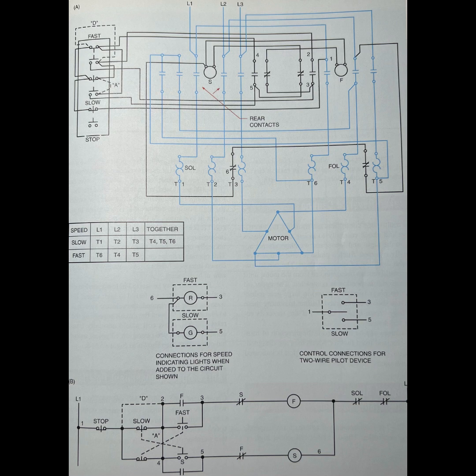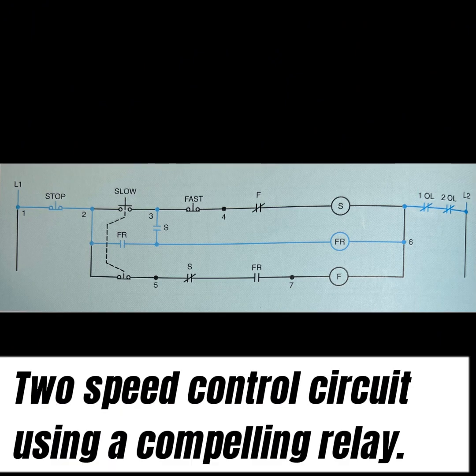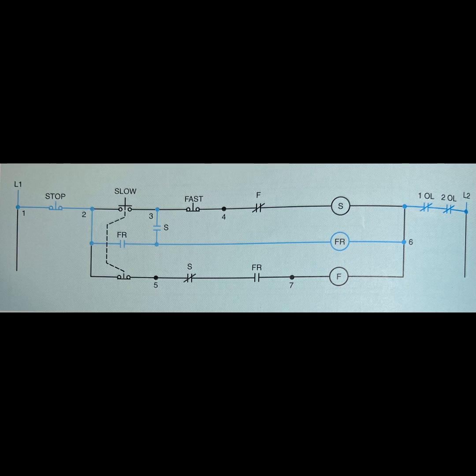Connections for the addition of indicating lights or a 2-wire pilot device instead of the control shown are also given. The compelling type control. These connections mean that the operator must start the motor at the low speed. This controller cannot be switched to the fast speed until the motor is running.